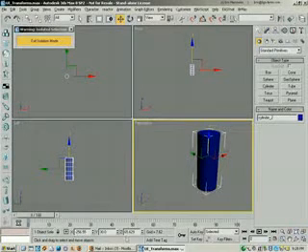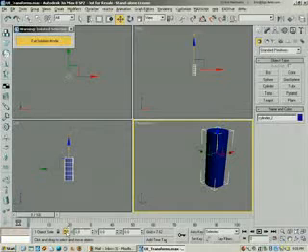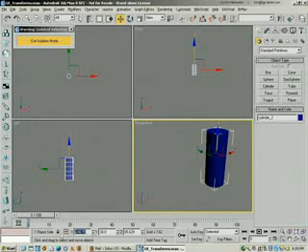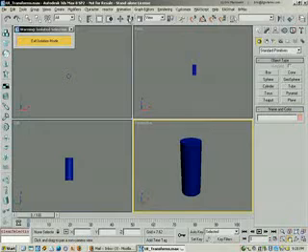Now if you don't want to see your world coordinates up here, you can click on this little button to the left of them, and this changes it to relative. So if say you know that you only want to move 10 units from your current position, you can turn on relative and type in 10 along the x-axis. Then when you turn it off, our value increased by 10 units. Okay, so let's move on to rotation and scaling.